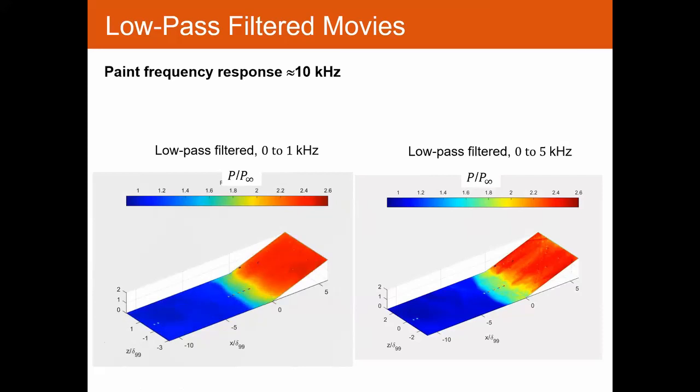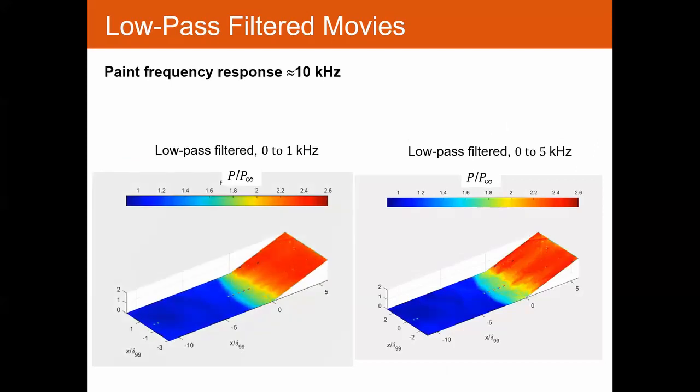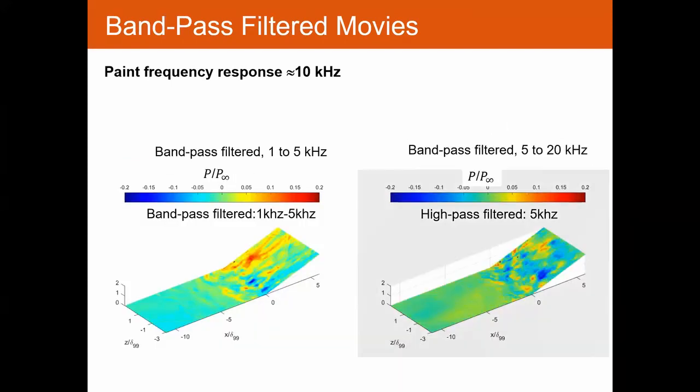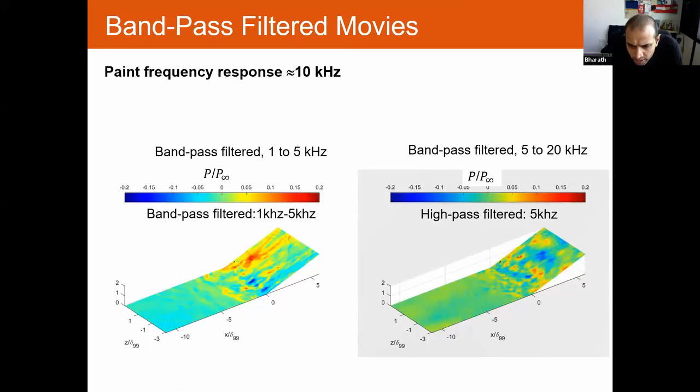And perhaps these bubbles may be splitting. If you look at the high frequency motion, it may be splitting in the span-wise direction also. Anyway, I think we need to look more for this kind of thing. Those are really good comments. Thank you. There's another comment from Lucaria, which said these could actually be the Görtler vortices. Yes, at least on the ramp, yes, I think they are.